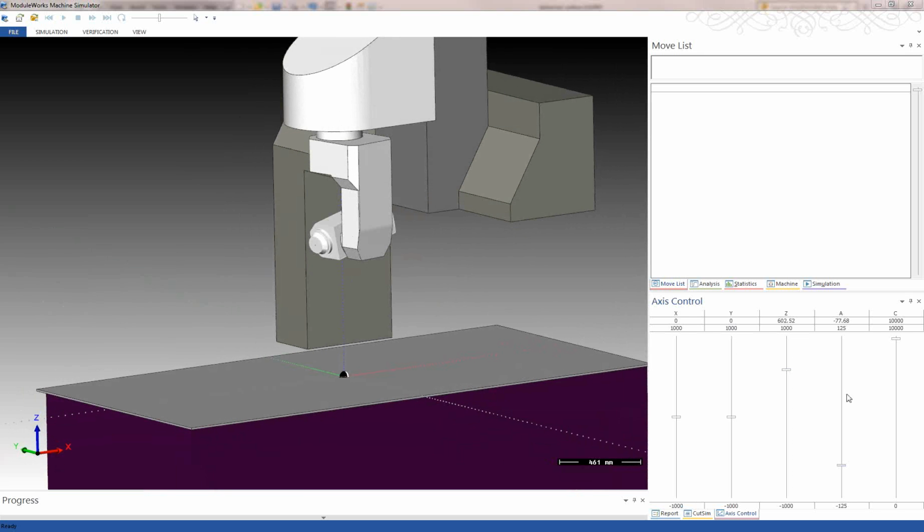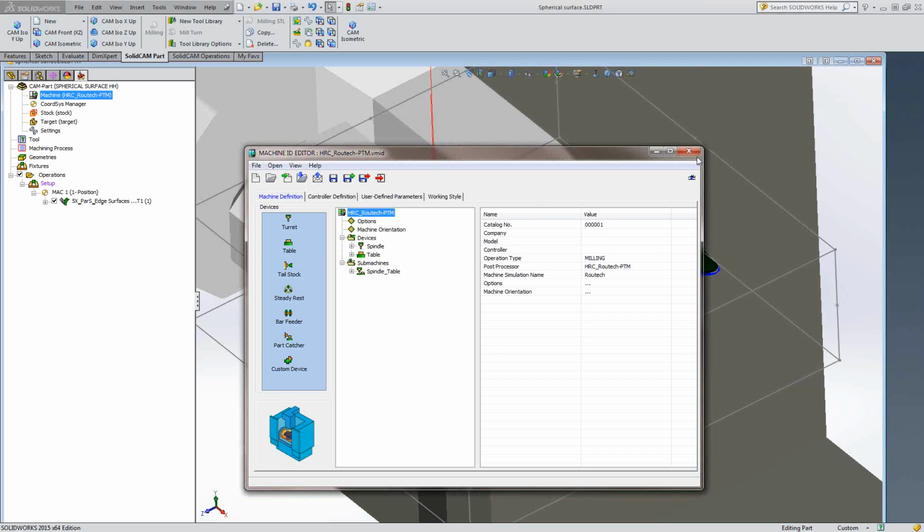But on a machine like this, the parameters would normally be set so that it would be between, say, minus 270 to plus 270 or slightly more. So as far as going round about an object continuously, this is not possible. However, SolidCAM copes with that and can show up any errors and give us a chance to fix them.